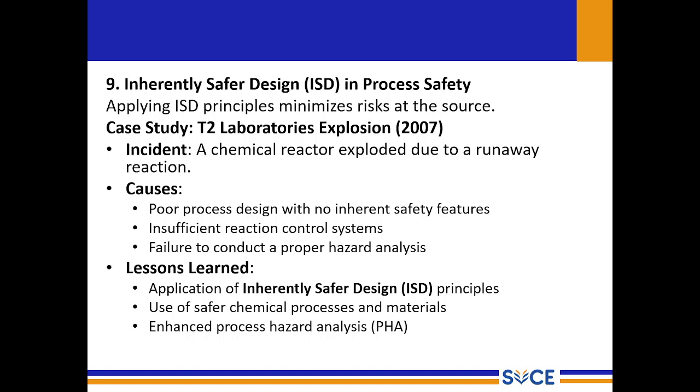So what can I conclude from T2 Laboratories? Again, I am confirming that the T2 Laboratories explosion demonstrates that process safety starts with the design. So design safer processes to eliminate hazards at the source. Implement automated reaction control systems. Conduct thorough hazard assessments, right? So this is the lesson we have learned from this.